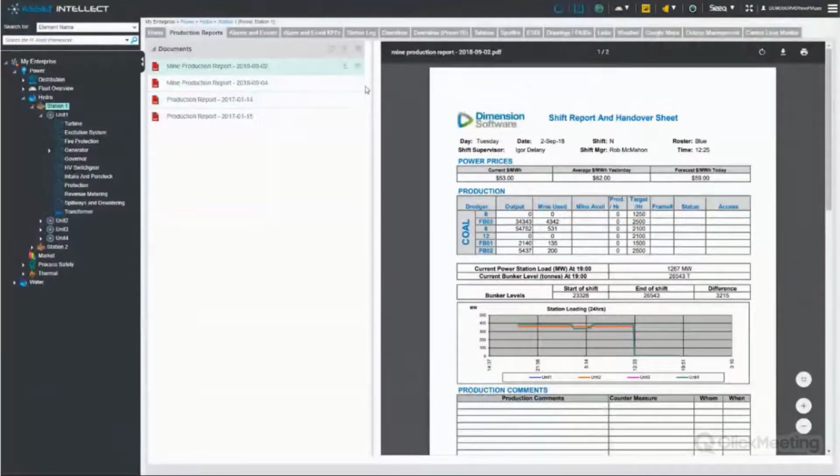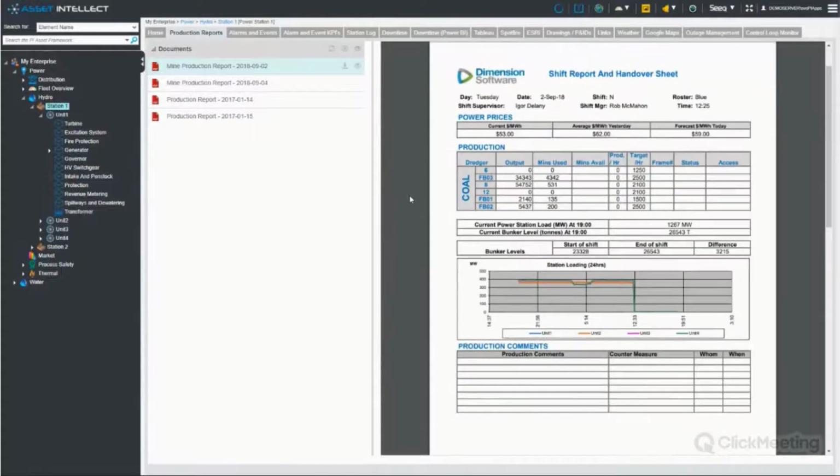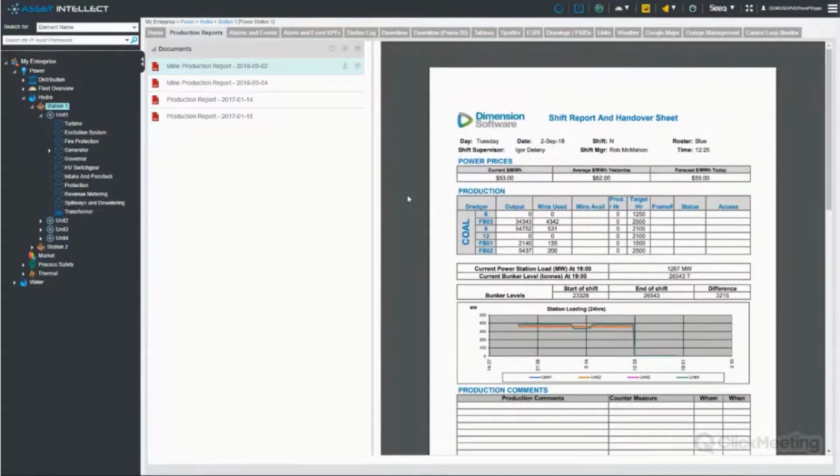So the reports can come out on a time basis, but they can also be generated on a condition, or an event frame. So if the plant trips, that will create an event frame, and we can then generate a report and attach it back into the event frame. So some really cool ways of orchestrating reporting and actually being able to distribute that report and attach it to an event frame as an annotation.